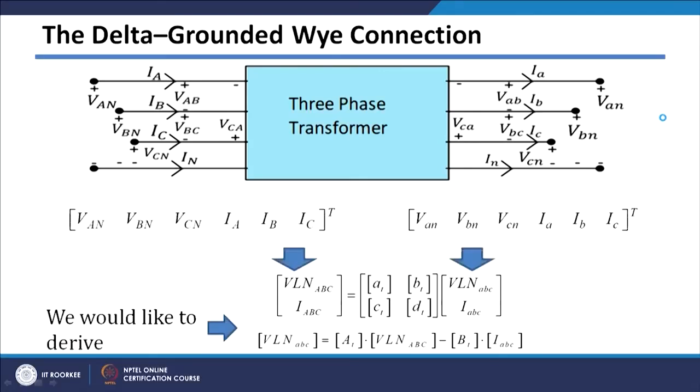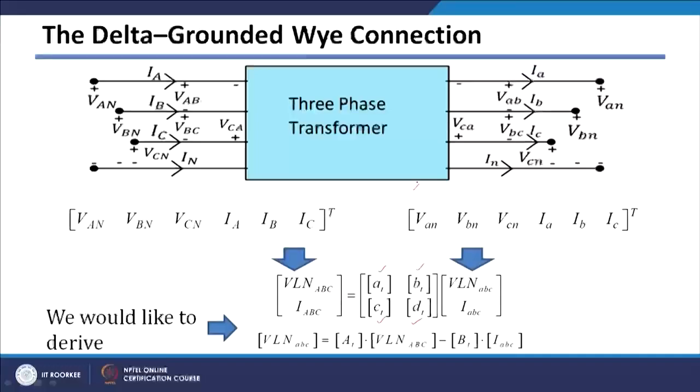Now in this case, in the three phase transformer also, we are interested in calculating these ABCD parameters. As I told you, once you know the ABCD parameters, you can write them in any terms, and it is easy to get whatever quantity you want on either side, source side or load side. Quantities can be easily calculated if you know the ABCD parameters of your component. So in this case also we need to put this three phase transformer into ABCD parameter format.